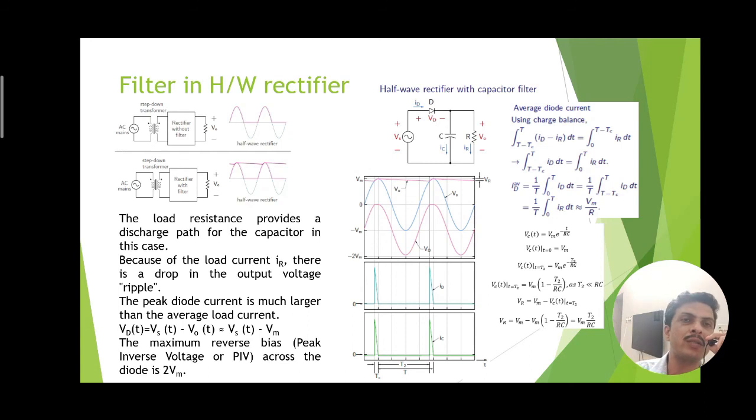So if the discharge occurs in the capacitor for a long time, it tends to 0 volts. Vc at T equal to Ts is given by Vm into e to the power minus Ts by Rc. If we calculate further, we can get the capacitive voltage at the end of the discharge. By considering the difference voltage, we can calculate the ripple voltage.